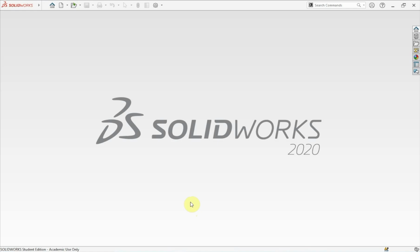Today we'll be designing a candlestick here on SOLIDWORKS. We'll mainly be using some new features such as Revolve extrusion, where we will be able to create cylindrical pieces, and we will also use another feature called sweeping or sweep, which allows us to create irregular figures such as curves or tubing. Now the piece I will be working on in this video is going to be a candlestick.